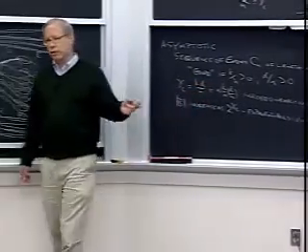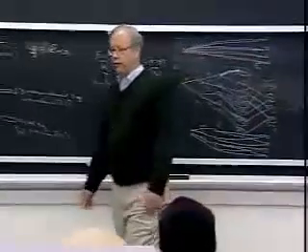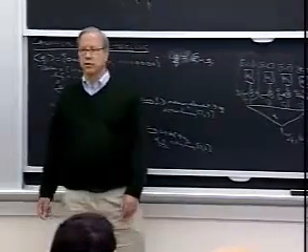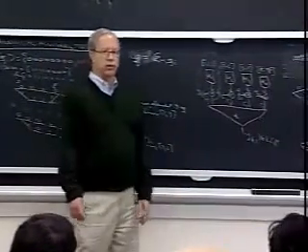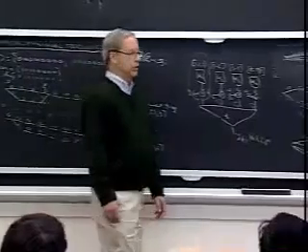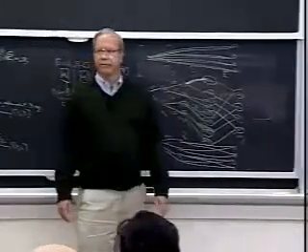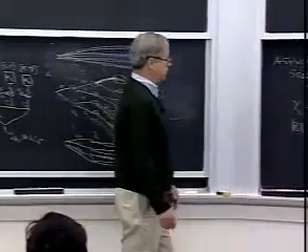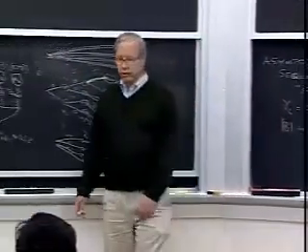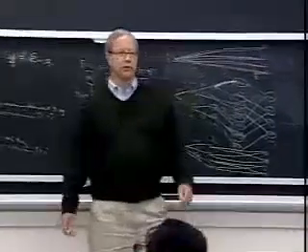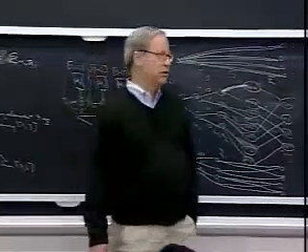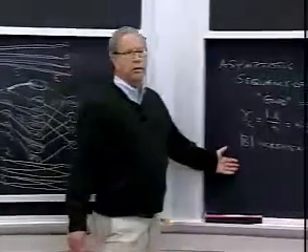And in fact, some of the capacity approaching codes that we're going to talk about, specifically turbo codes, tend to have bad minimum distances. You can have a turbo code that's thousands of bits long, and its minimum distance will be something like 20 or 30. And yet it signals within 1 dB of the Shannon limit. It gives you low error probabilities within 1 dB of the Shannon limit. So maybe there's another way to go.